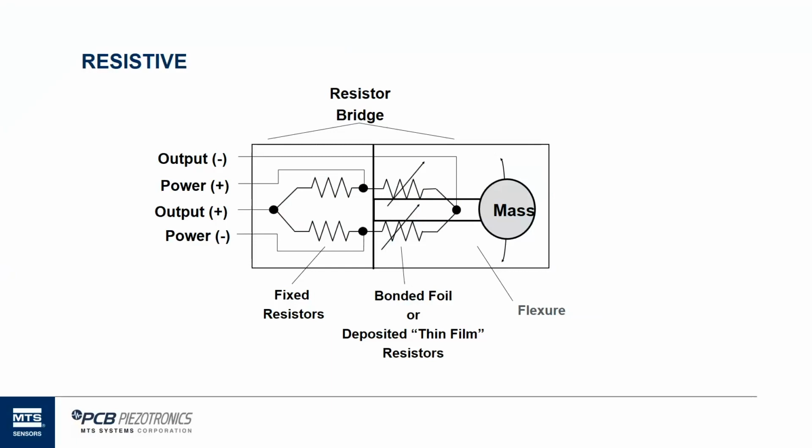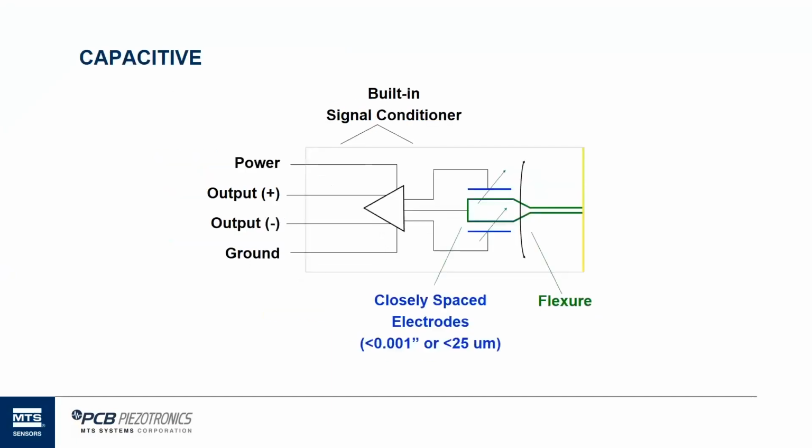And that is the basic concept of the piezoresistive, aka resistive type sensor. The next diagram, we see this is what we call a capacitive type device, where instead of using strain, again, you see on the right-hand side, the green element there is another inertial mass. Again, it's that consistent element we have in all these. And while the cantilever beam extends to the right, we're not using that cantilever beam for its strain characteristics.